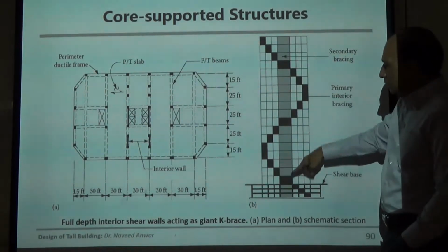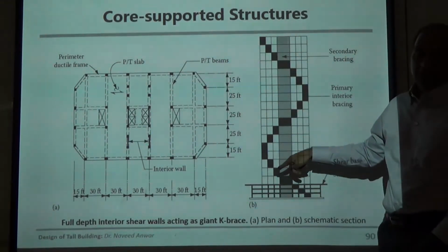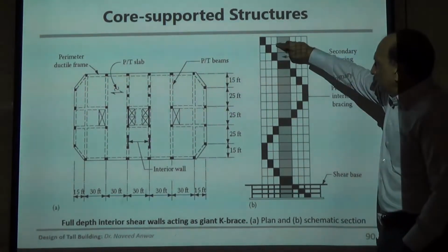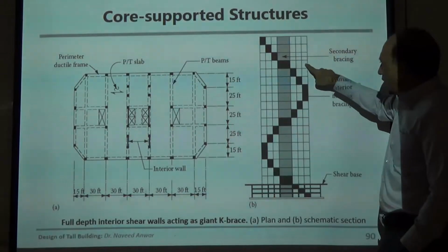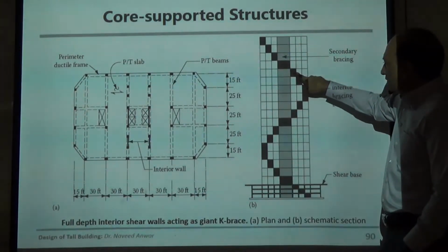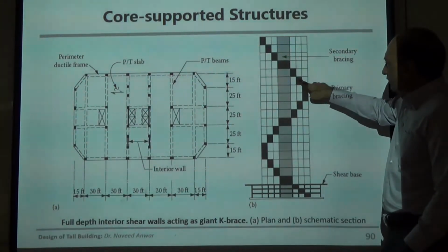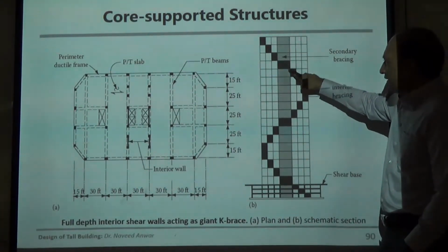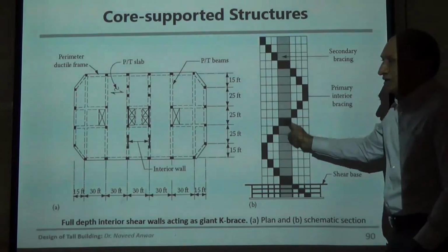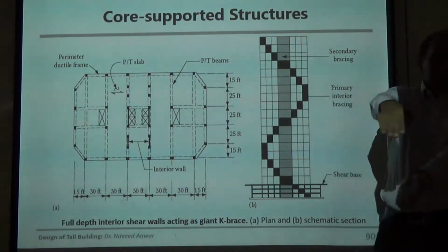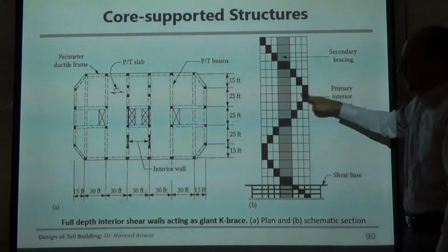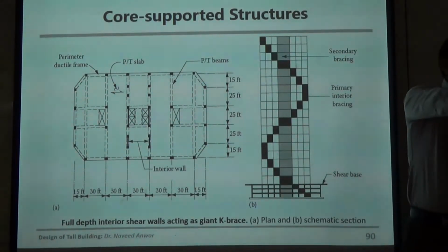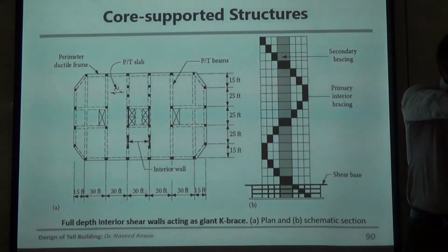There are many ways. This is one. We used it in some buildings. In fact, we used it in Manila, the tallest building there. That is the core wall. So these are the columns. Every floor we find one wall, one panel, and make it concrete. So it starts to act like a truss, right? This one and this one act like a truss, and this becomes very strong, like a coupling beam, but a very big one, like a cantilever.